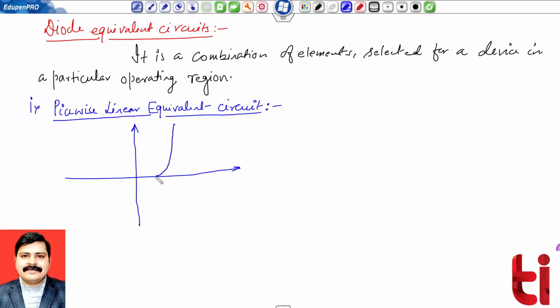It seems like this is the curve. We are mostly interested in the forward bias region. This is my ID in terms of milliampere, VD, volts. If you can check, this was my knee voltage VK I have represented, reverse bias case, forward bias case, and as it is a bit slopey, I can say that there will be some average resistance. Our average we can mark.